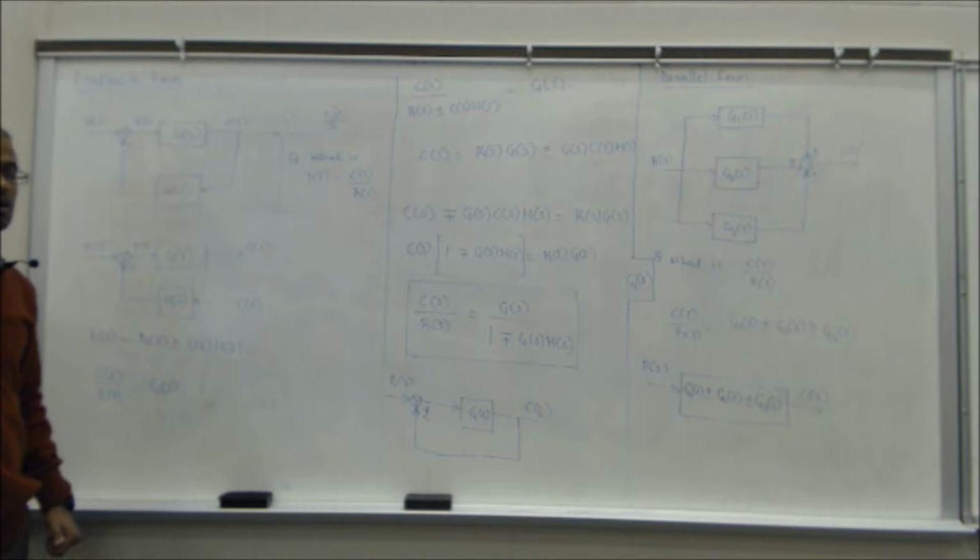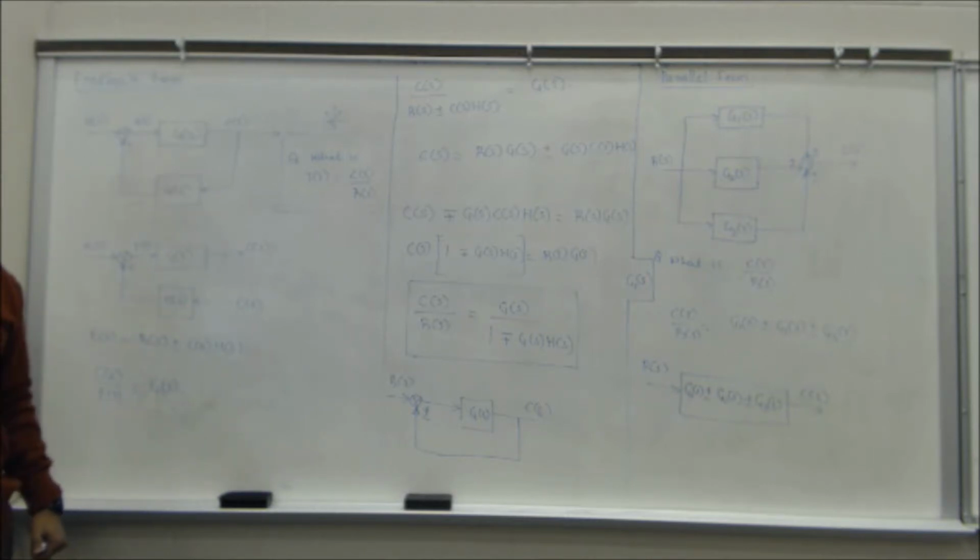Now think about a toaster. Toaster is a control system, right? It is not sending a signal back. It is just time based, right? So that's an open loop system. You're not feeding back anything. If you were to feed back, let's say, the color of the toast or how well the bread is toasted, then it could be a closed loop system.